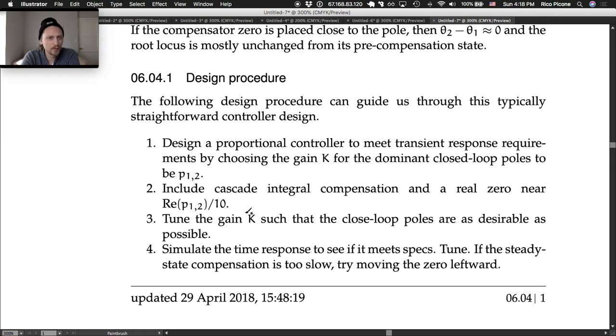You can set up loops. I noticed that some of you in class were already doing that with the proportional gain to try to get a certain settling time or something like that by just putting it in a loop and evaluating the step response using step info. So yeah, that's a great way to do it. You can also do that. You can automate the process of searching for the gain, in this case, too, for the proportional integral controller.